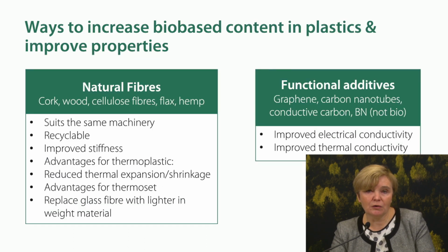Bio-based content in polymers can also be increased using different natural additives. For example, natural fibers. This is one of the very common options at the moment, and this type of polymers is already possible to find. So one of the advantages is that you can exchange up to 50% of the polymer which is produced from synthetic sources with the natural resource.